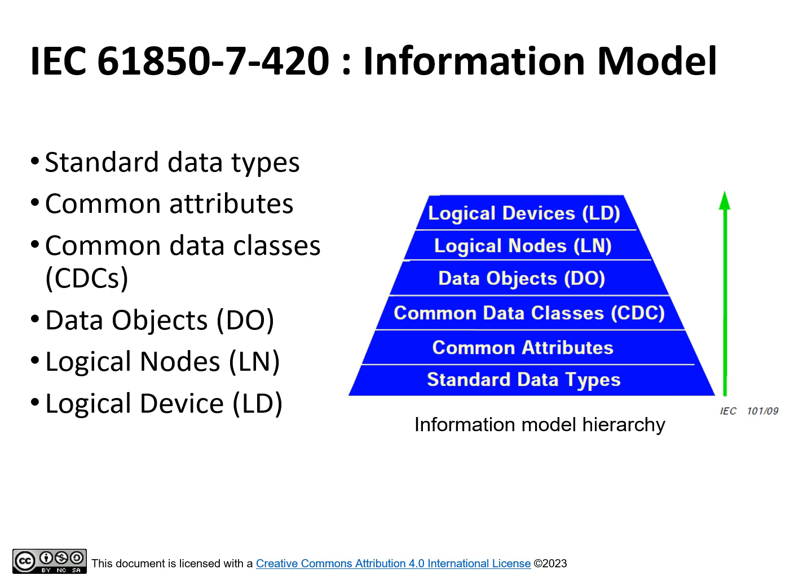Examples of LNs include MMXU node, which provides all the electrical measurements in three-phase systems such as voltage, current, watts, VARs, power factor, etc. And XBCR node for a circuit breaker with a short circuit breaking capability.